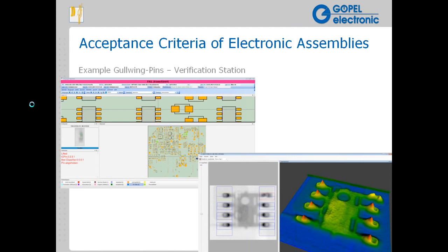Here again is another example. This is an example that's actually quite dramatic and surprising in a number of ways. When you look at the optical images on the left, it's not real obvious that there's a problem here. Very careful programming in AOI would likely catch this in most cases, but I know for a fact that we've seen many escapes of solder issues like this. And if you look on the right, the X-ray image and the topo view images, a problem becomes much more prominent.